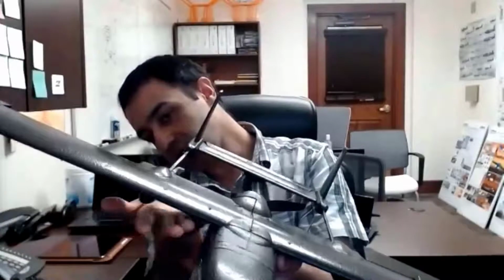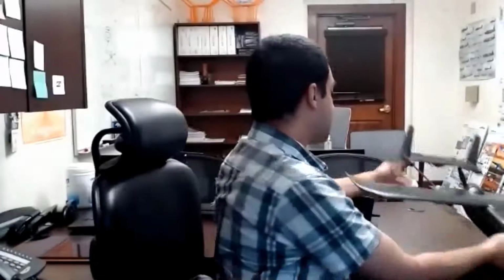So if you want to have an airplane which has this angle, this airplane doesn't have the dihedral angle right now, but if this airplane has a dihedral angle, and I have a disturbance on this side of the wing, this will be tilted, right? Then this projected surface area, if I project this, is going to be less than this side. So the lift which is generated on the left side is going to be more. So I have more lift here, so my airplane is tilted. Once the lift here is more than this side, this will be returned back to the original. And this is the main reason that we have this dihedral angle, specifically in larger airplanes, for stability.